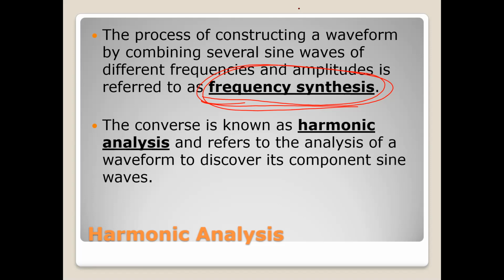And you would have applied this principle when you were doing rectification. Now, it may not have jumped out at you, but you really have done it. And I believe everybody in this room has done rectification. But beyond rectification, what you had to do to get your waveform smoother was to create a filter. And the filter that you would have looked at at your level would just be to put a capacitor in parallel. That's one option. Or you would have put an inductor in series.